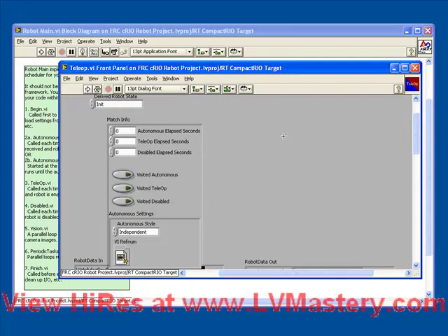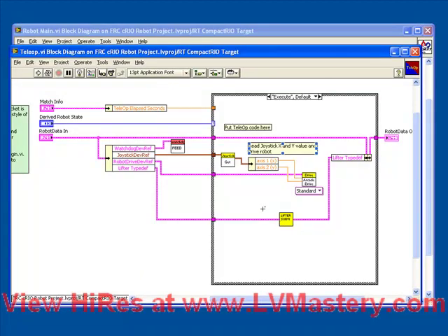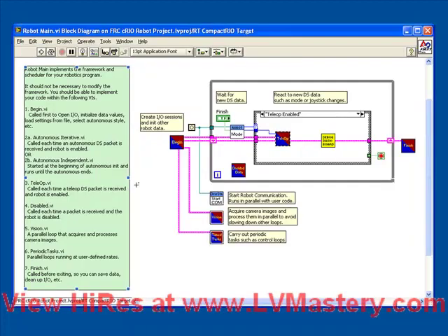We'll open up Tele-Op, we'll go to the code, we're going to cut our sub-VI, we're going to remove the bundle by name, remove all evidence that we were dealing with that type def from our Tele-Op.vi, and we're going to paste our sub-VI into the root of robot main.